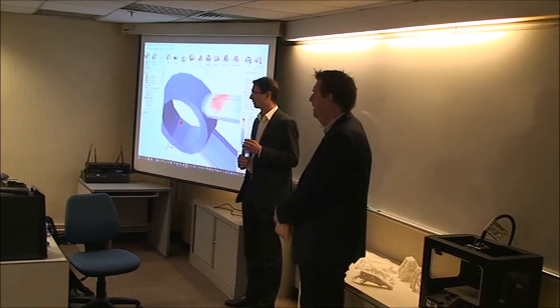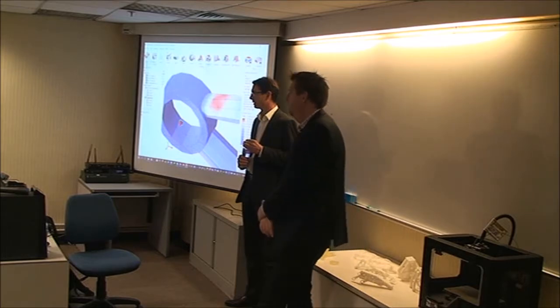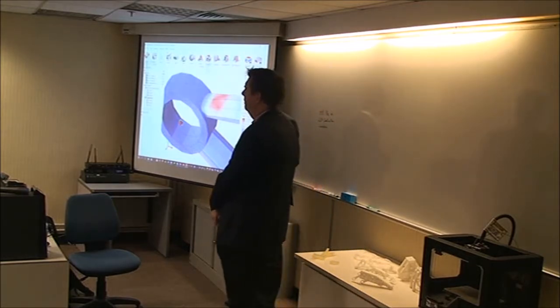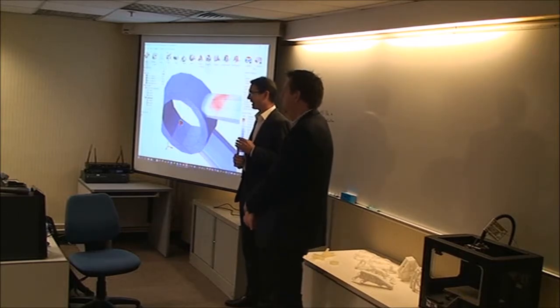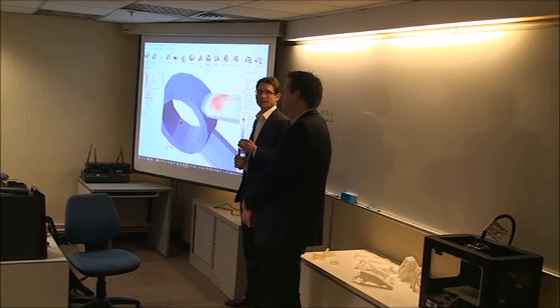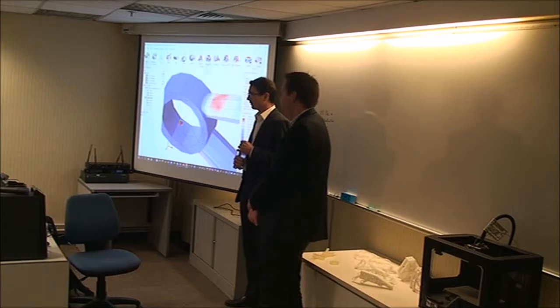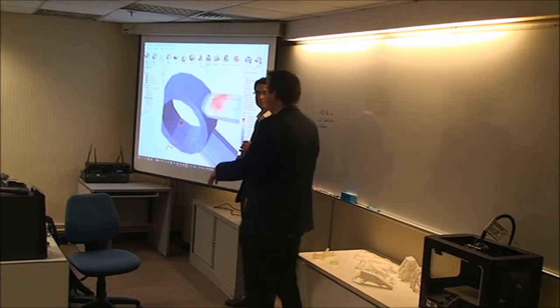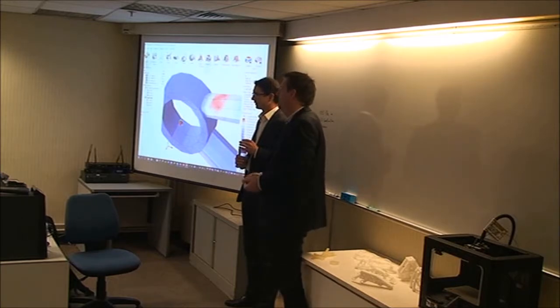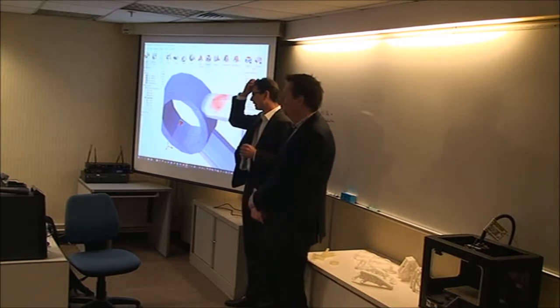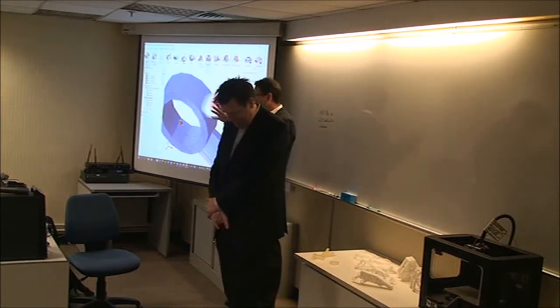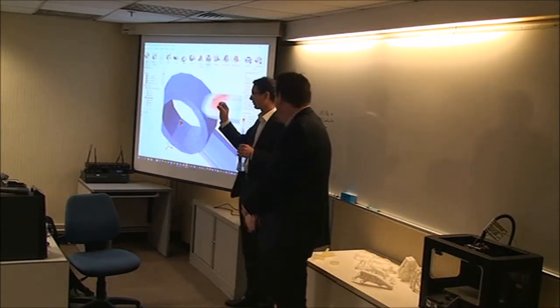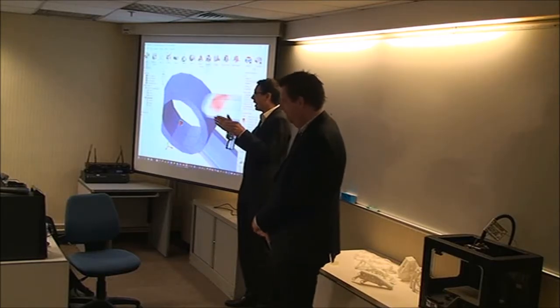So all the materials specified under this software, like titanium. Yeah, but there are a lot of titaniums possible. They have Ti-17 or 6211. They're just generic values. They're not actually a specific material. They'll be from the metals handbook or somewhere. But every 3D printed material will be different. It gives you a value where there is a material out there in the world which 100% fits that value, but there are a lot of variants possible.